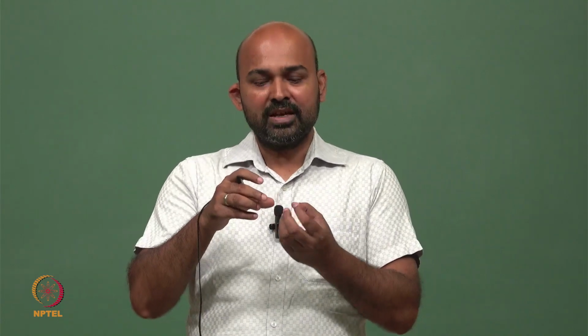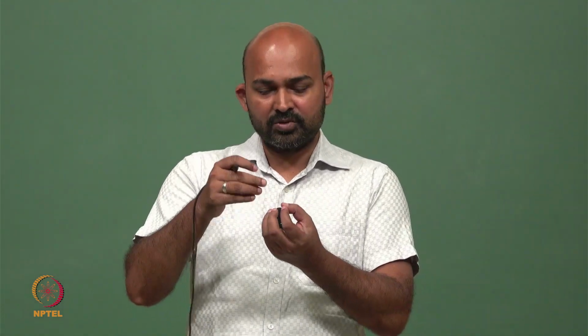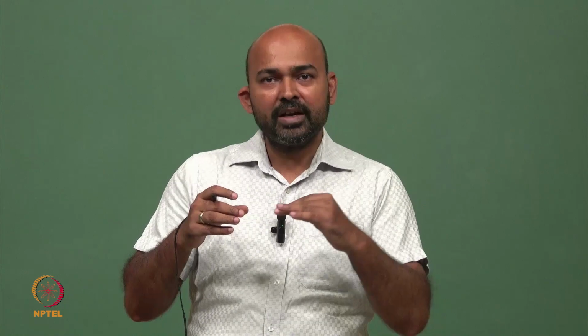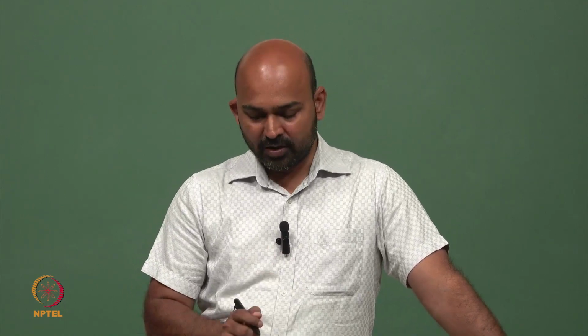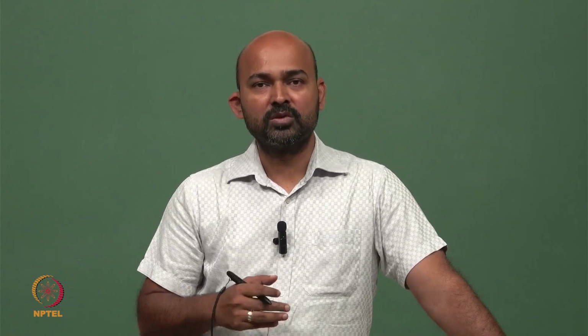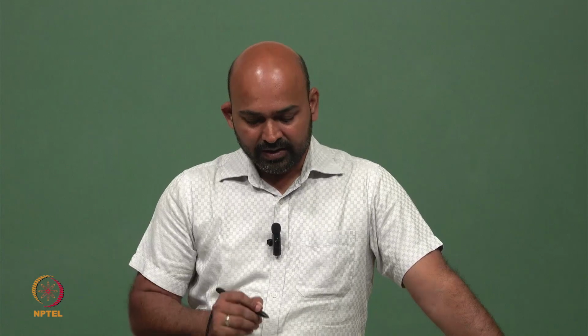These heat sinks have small fins, and we force air through those short fins to dissipate the energy to the outside environment, or use guided, directed air flux down the longitudinal fins. So this is also another type of heat sink. Let's discuss a little bit about these heat sinks.